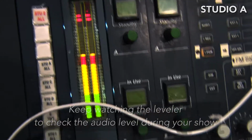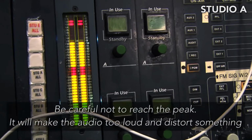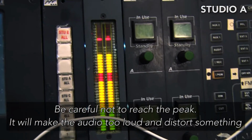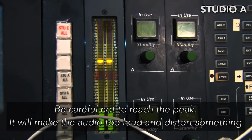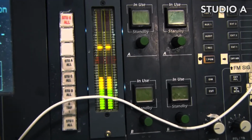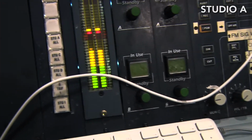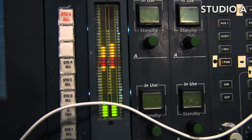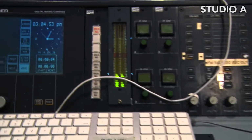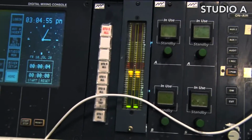If you see it do something like that, where it's just bouncing all the way up, you're kicking in the compressor in our audio chain, and it sounds pretty bad on air that way, and you're probably distorting something as well. So just stay away from really running this too hot. You want to keep it right around there. But like I said, just engineer everything to -15 and make small adjustments from there. So that's your visual monitor.